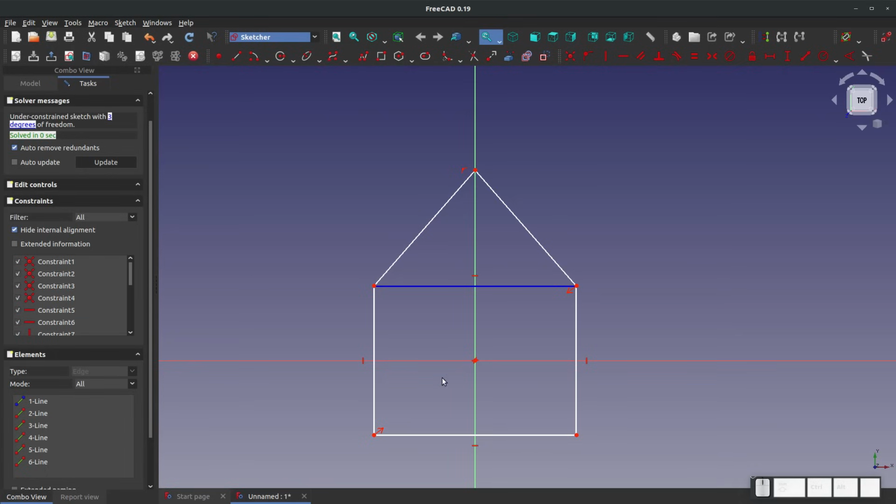Likewise, maybe I want the elements of this house to fit around a circle. Well, if I hit this button without anything in my sketch selected, then it changes my sketch tools over here to be blue. You can see how I toggle them from white to blue. So maybe I'll draw a blue circle around my origin.